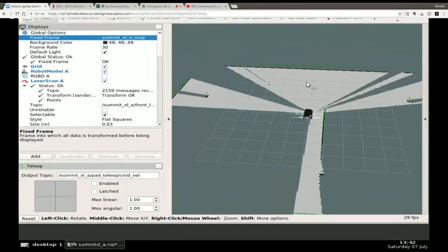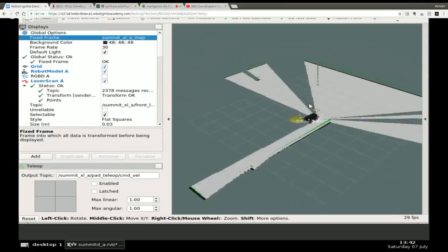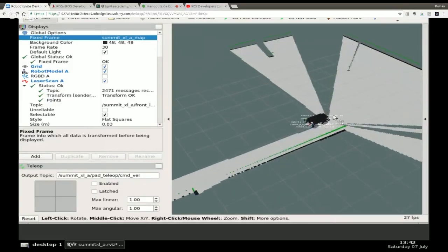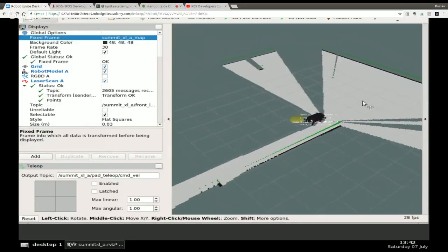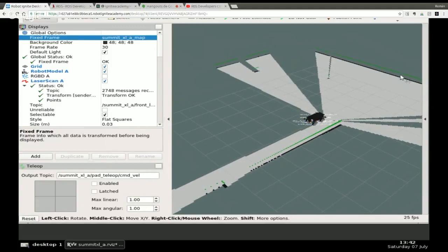If we want to have good quality maps, it is important to have a good odometry estimation and a good laser range to be able to detect the walls always. If we are in a really big area and the laser is not able to detect any wall or obstacle, gmapping is not going to work because we need that information.